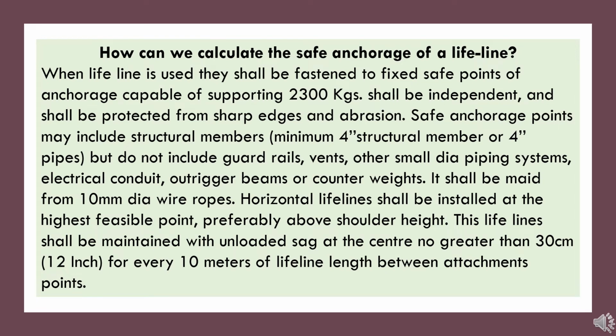How can we calculate the safe anchorage of a lifeline? When lifeline is used, it shall be fastened to fixed safe points of anchorage capable of supporting 2,300 kilograms. It shall be independent, and shall be protected from sharp edges and abrasion. Safe anchorage points may include structural members, minimum 4 inch structural member or 4 inch pipes, but do not include guardrails, vents, other small diameter piping systems, electrical conduit, outrigger beams or counterweights.